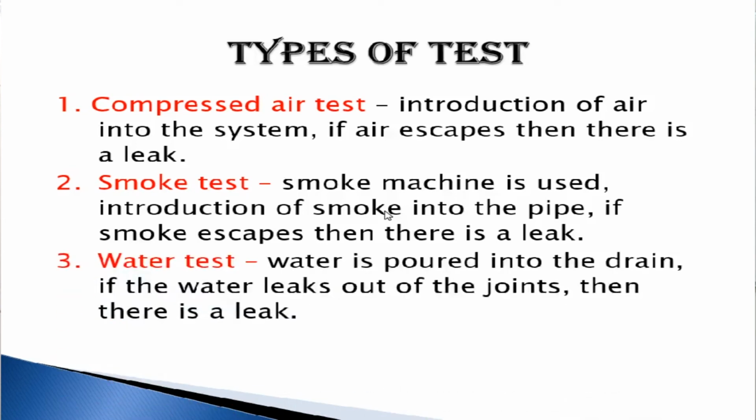The preferred method is a water test. A water test can only be done in dry weather conditions. Water is placed into the pipe. If the water escapes at the joints, we know there's a leak and it needs to be repaired.